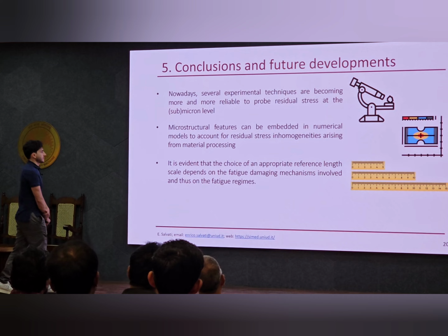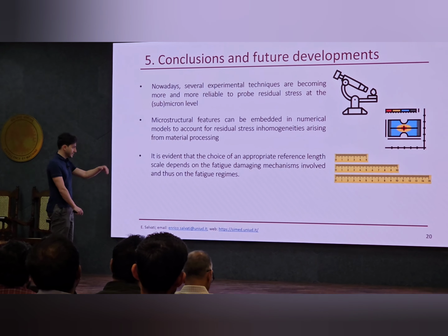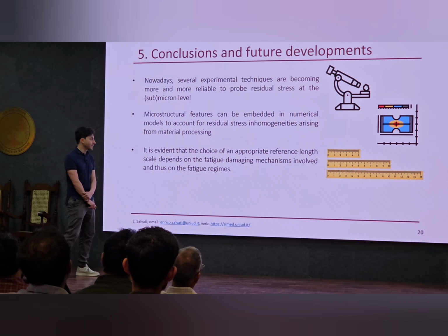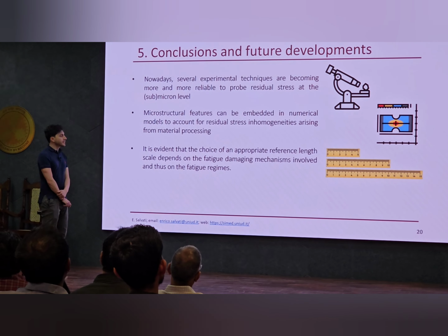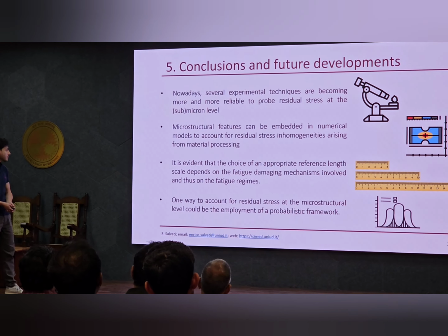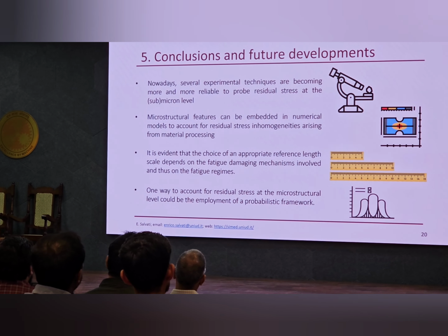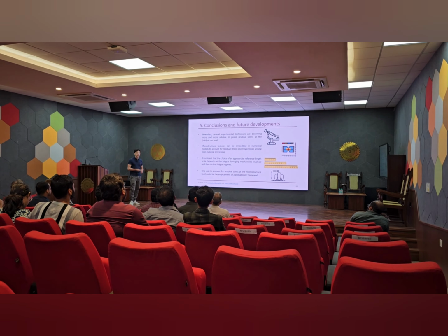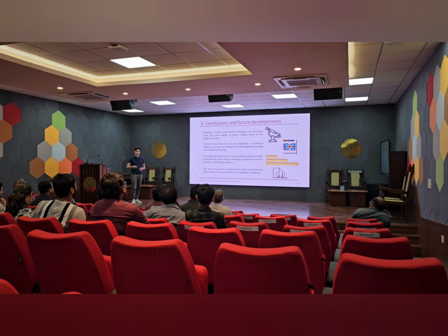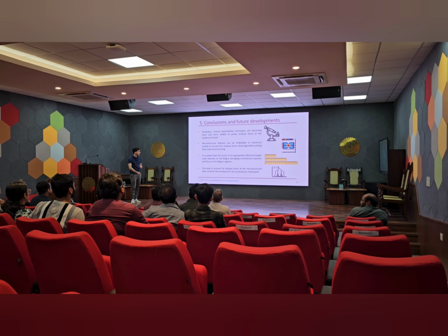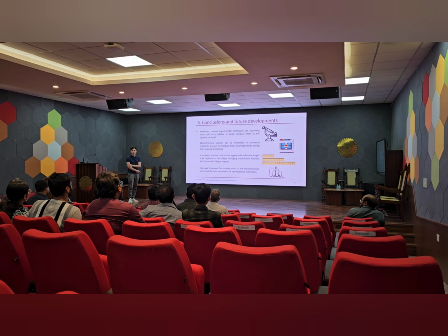It is evident that the choice of appropriate reference length scale depends on the fatigue damaging mechanism, and therefore on the fatigue regime. And this is something maybe more subjective, but I think one way to account for the stress in the future, talking about 10 years, 20 years from now on, is to approach the problem with probabilistic methods.